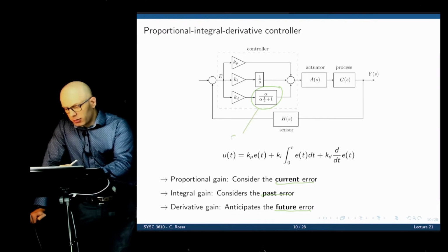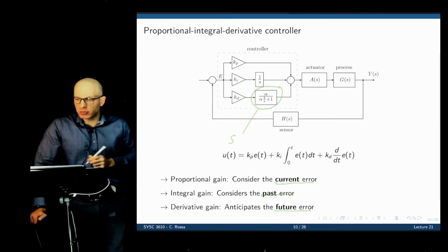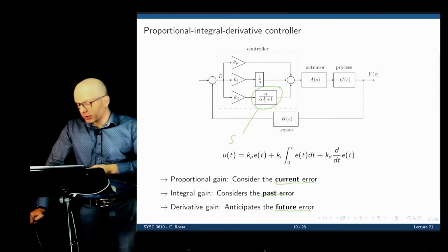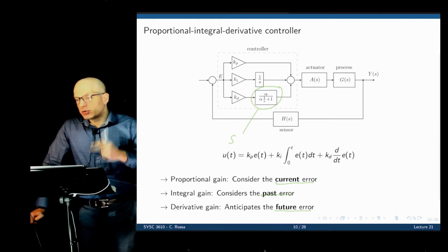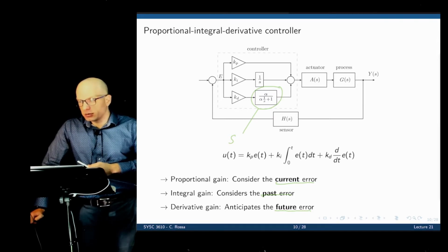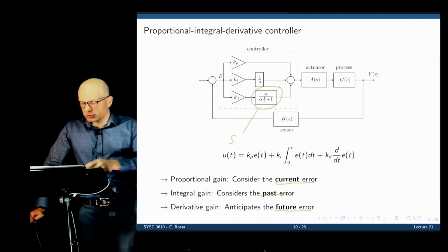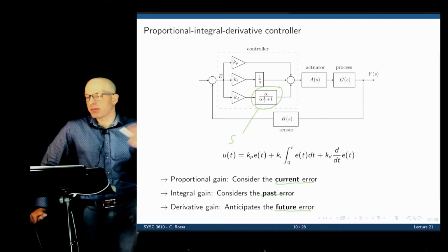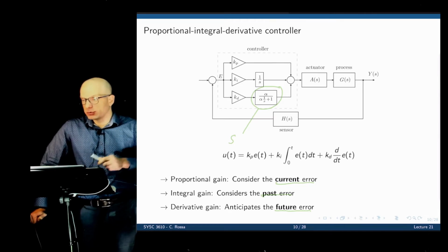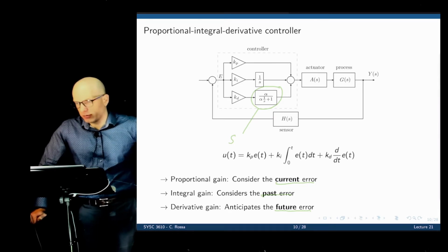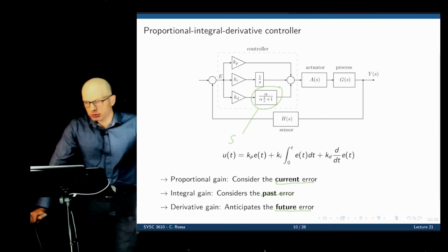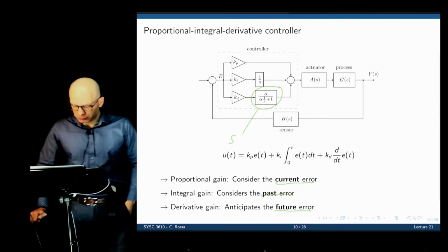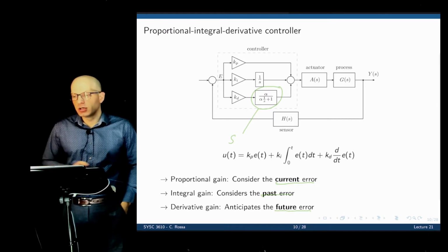This is the s operator, but if you use Simulink and you put a transfer function with the s, it's not going to work because we have what we call an improperly defined transfer function, where the degree of the numerator is greater than the degree of the denominator. And Simulink doesn't accept that, so here's a little trick to make that go through. If we make s over alpha with alpha a very large number, this works like a low pass filter with a very high cutoff frequency, and works like a derivative operator. It's just a trick to be able to implement this in Simulink if you have to. But it's essentially the s operator.